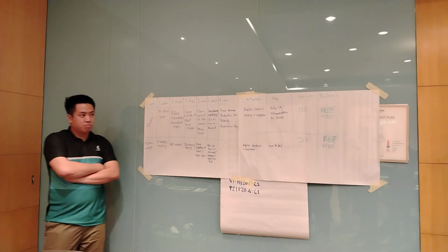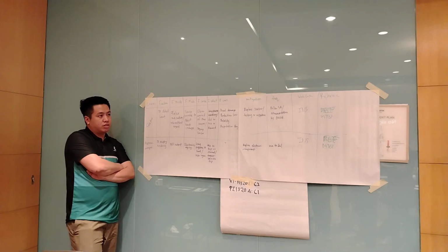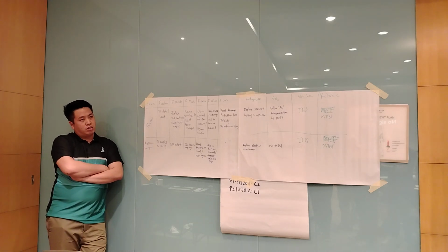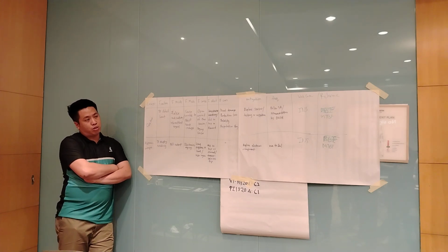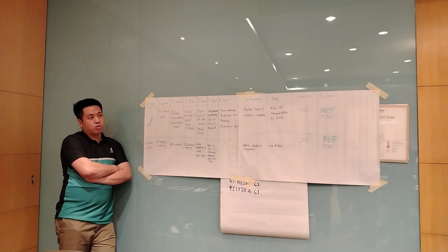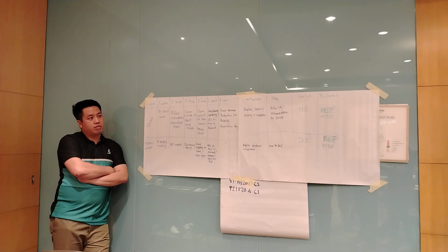So what does IPF usually say about the sensor inside the enclosure? Usually what we can do is wait for an opportunity, because they have their own voting system, like 2 out of 4. Once it is 2 out of 4, if it's really hit, you start to trip.